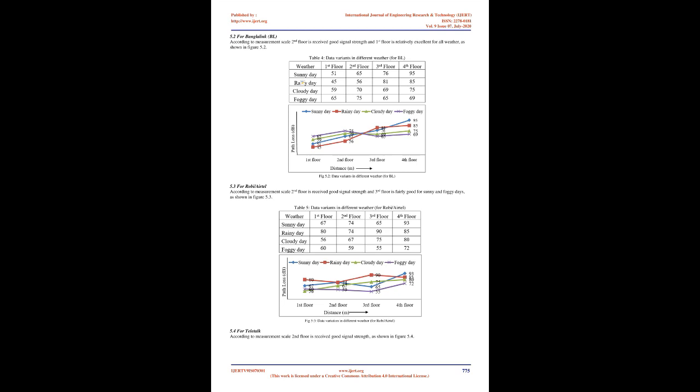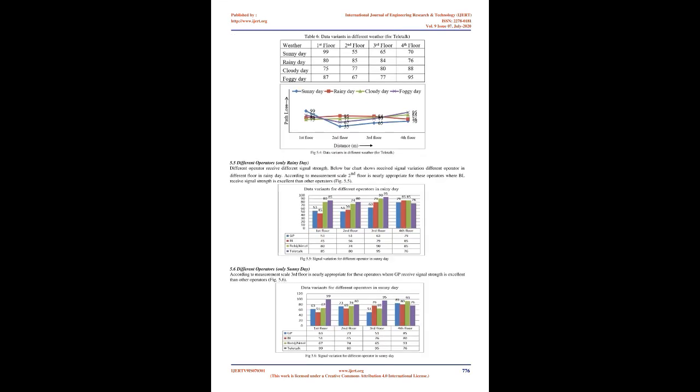4.2 Signal strength calculation, A, for the case of cell phones. To measure the power of the signal received by the antenna, the numbers are usually reported in dBm. Since this is coming from a controlled impedance antenna and transmission line, we need to use RMS voltage or current. For example, let's say we measure the RMS voltage to be 2 mV, and we have a 50 ohm antenna system. The trouble with this method is that it is actually not measuring the signal, but all electromagnetic energy received by the antenna. That is, it also includes noise. The signal might be strong, but the noise might also be strong, so the signal quality will be poor.